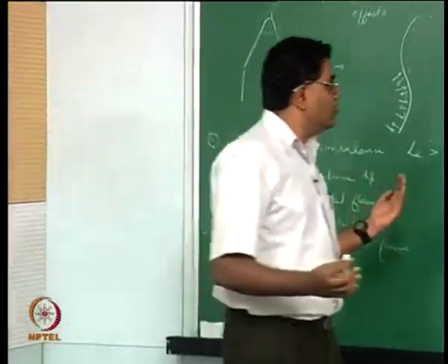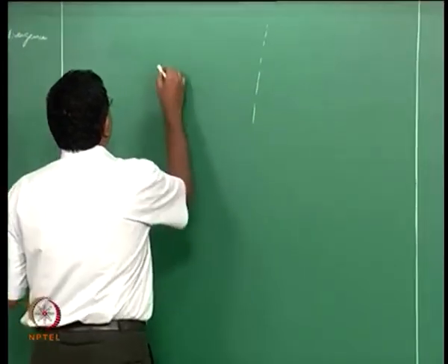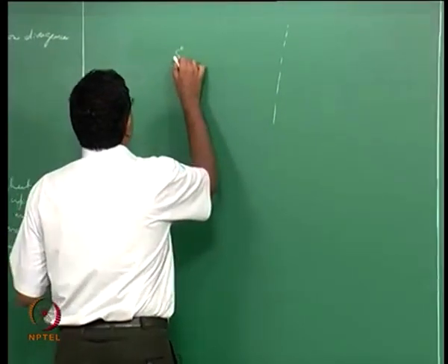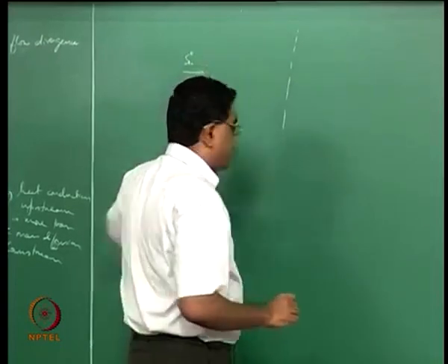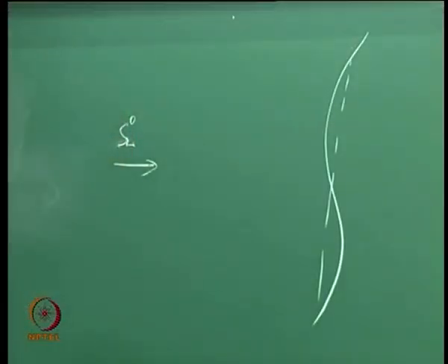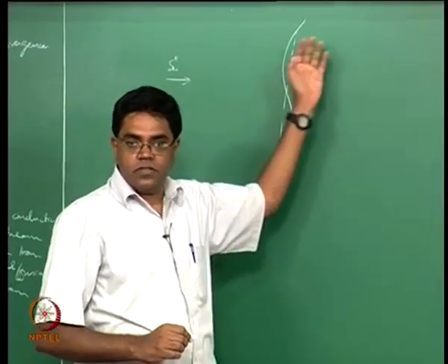So we try to still go through the same idea, that is you now have a nominally flat flame with an S_L naught, but then now you are beginning to think about the fact that the density of the products is going to be less than the density of the reactants and perturb the flame to be non-planar. Alright. So as a consequence of the density difference, local mass balance dictates that the velocity should compensate for it.